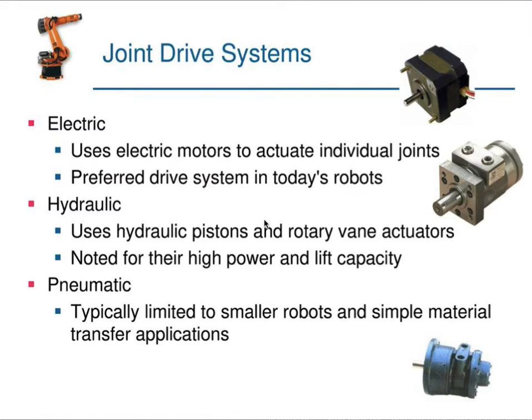Among the electric actuators, the step motors and the direct current motors, which have constant inductor flux, generated either by a permanent magnet or through a constant inductor current, and are controlled by the armature current, are used efficiently.